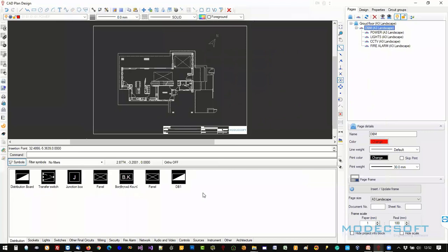Successful save symbol. And this symbol will be presented here. Okay, this is my symbol. Now, because eventually you're going to have many symbols here, you can move the symbols you're using often to the start. So I'm dragging and dropping them here to the start of the list. So I don't have to look at them.